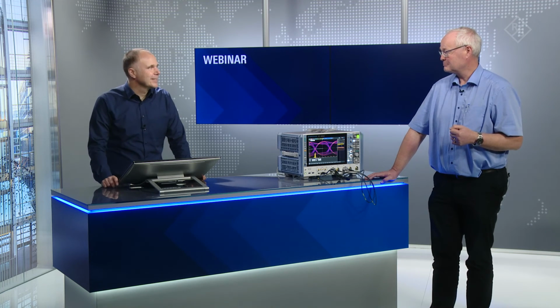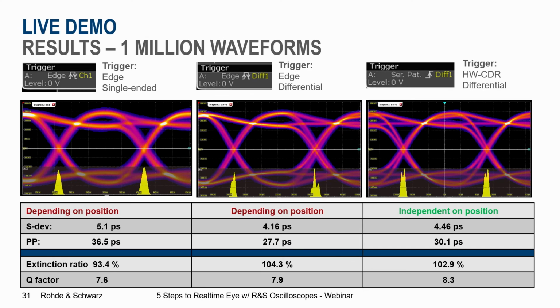Thank you, Matthias, for this interesting demonstration. As you knew what Matthias is presenting, I would like to show you a quick summary of the results. So maybe on a slide, it's easier to see. In the first step, Matthias used just an edge trigger. So here you see the edge configuration on a single-ended signal. And you can read the standard deviation of the first histogram, the peak-peak jitter of the first histogram, and also the extinction ratio and the Q factor on this eye. Very important for this first approach, it really depends on the position of the edge. So if I go to the next edge with my histogram, the values always will be different.